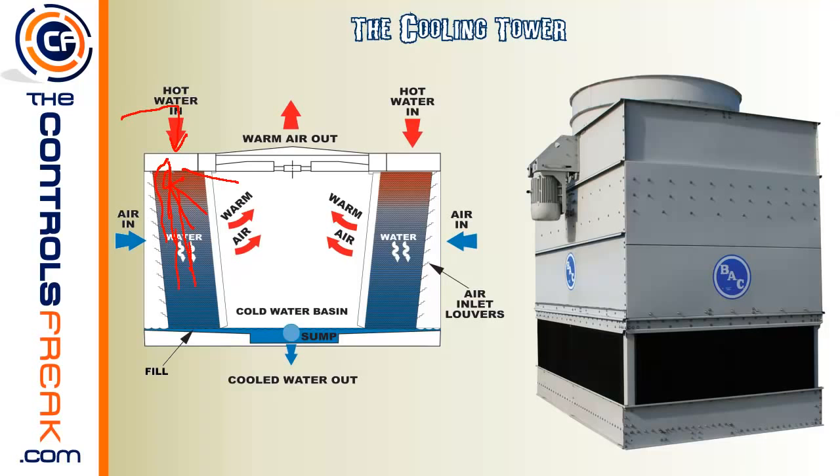Now raining down across just by itself would actually help cool the water down, just with the air naturally coming, with the water pouring out and going across these little fins that are here. That'll actually give it a little bit of cooling. So sometimes you'll actually use that as a first stage of cooling.